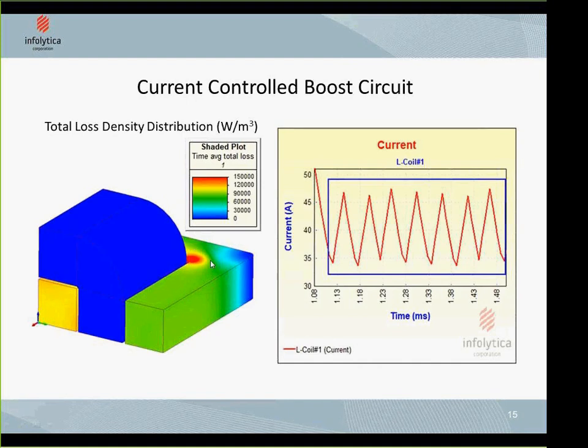The other key advantage of MagNet, another important feature, is that I can determine my window for analyzing the losses or for averaging the losses. At face value, it might look like it's not important, but if you are doing fault analysis, or transient analysis, or load variation analysis, then it's a key feature, because I can determine my averaging window depending on where I want, and with that, I can analyze the impact on my device. Is my device still within my design window, or does it still meet my design criteria?